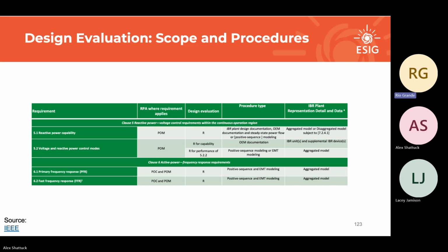There's no maximum effort where we're going to say stop doing work for grid compliance. And testing Q control mode is just probably 3 lines of code in your automation script and 30 extra seconds. Because it's literally just testing to make sure you go to a Q set point. It's one of the easiest tests to run and verify. Right? If I put 10 megavars in my plant controller and I get 10 megavars at the point of interconnection, that's great. If it's wrong, then it's a really easy thing to suss out. So those are 2 major pieces to talk about there.